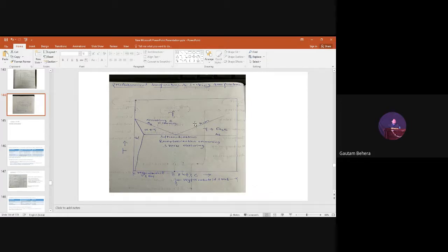So our priority is to have cementite in a discontinuous way, or in a spheroidal or spherical form. That is good. Always remember, since cementite is a very hard and brittle phase, it is basically a weak portion of the steel. It is a weaker region. Crack always initiates from there. But if the cementite is in spherical form, that is good. But there should be a uniform distribution of spherical cementite, right?